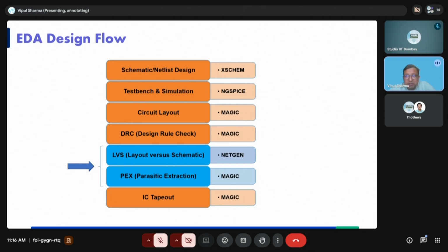And then there are some other steps which need to be followed, like doing a metal fill on your design layout. But in our case, since we are planning to do this tape out through Tiny Tapeout, these things need not be taken care of. The objective for people who want to send their design for fabrication is just to complete the layout of their block, and then they can submit to us, and we will take over from there for making it compatible for fabrication.